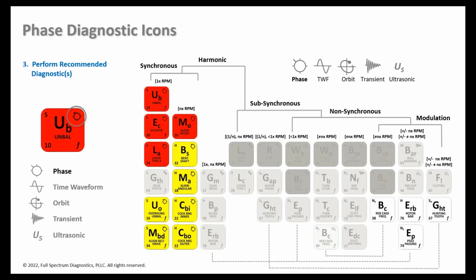It takes you about as long as I just talked. Take a spectrum. What's the dominant peak in the spectrum? It's at turning speed of the shaft. We go from 35 down to 11. Now, what direction is it? Well, it's in the radial direction. Then we pull 6 more of these icons off the table, because if it's radial, it's not axial.